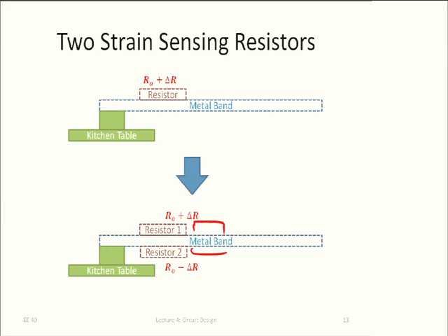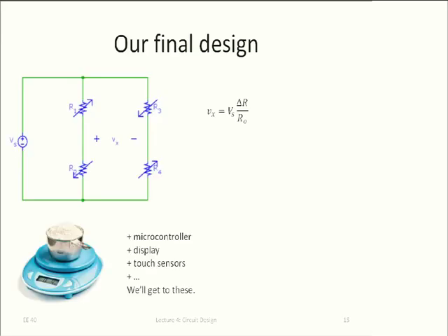it, okay? So now I have these 2 resistors both increase when I increase the weight here and bend this thing, and these 2, A and B, they actually decrease. All right? And out of that, I can build the circuit that I showed here. So that's now a fully balanced circuit. It's actually called a full bridge circuit, whatever its name, right? And it has these 4 resistors, 2 increase and the other 2 decrease.